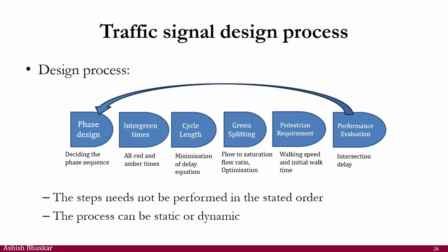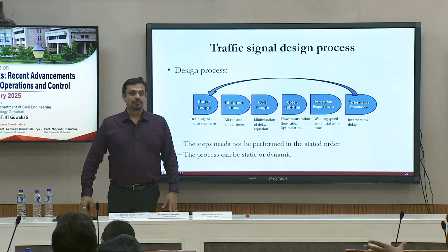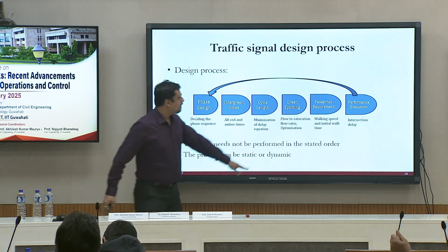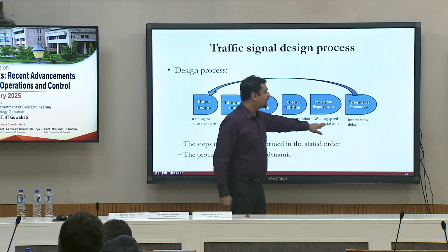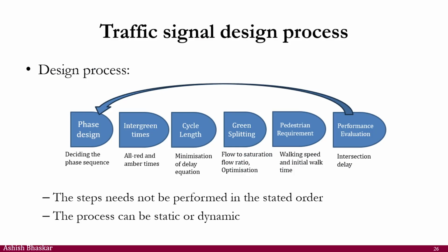Can we come out with some different loss if it's happening because of waiting period? Yes, that's what we say, performance evaluation. At the end of the whole process, for example, there is a delay equation, maybe a Webster delay equation, or you can use some other modeling tool, let's say Sidra. That will give you the amount of delay for all the approaches after your signals have been optimized, and that delay you see whether it is acceptable or not.